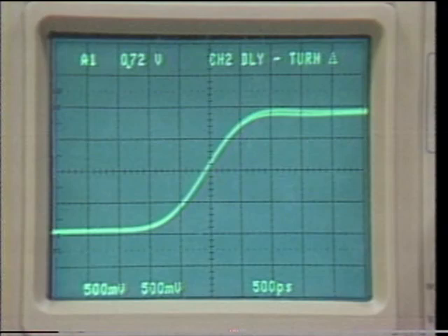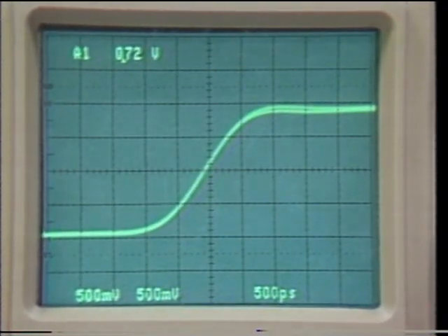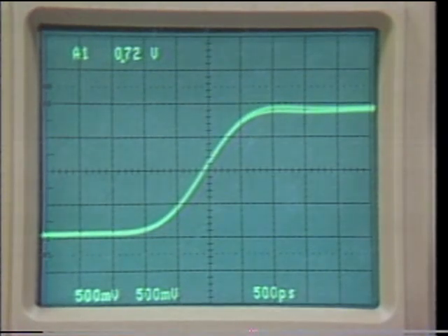Then when we push the seconds per division knob back in, that setting is stored in a non-volatile memory. And every time we make a propagation delay measurement in the future, that information will be used.